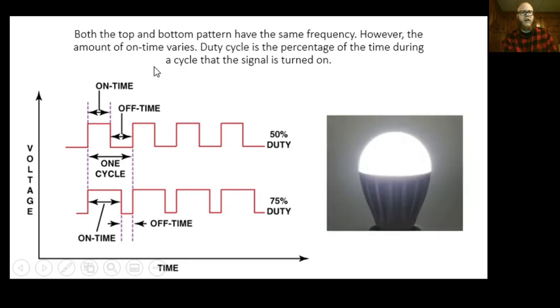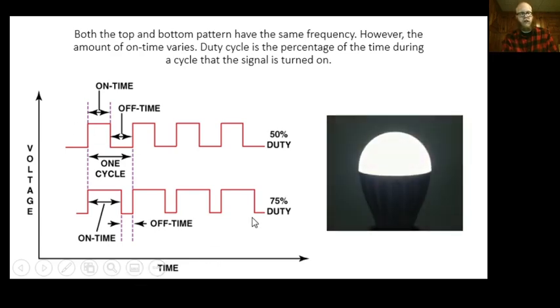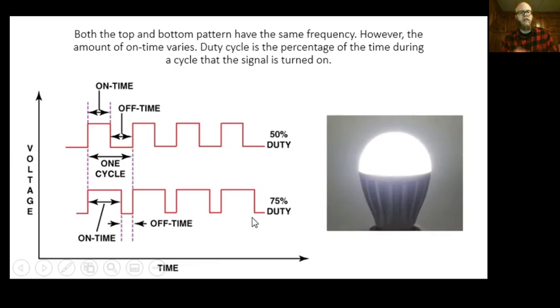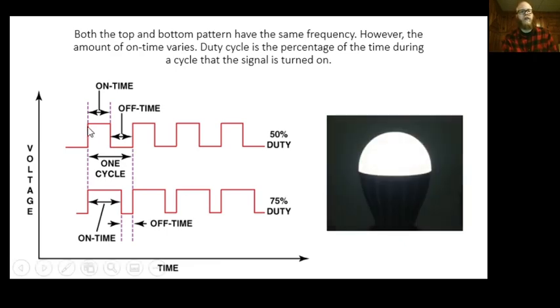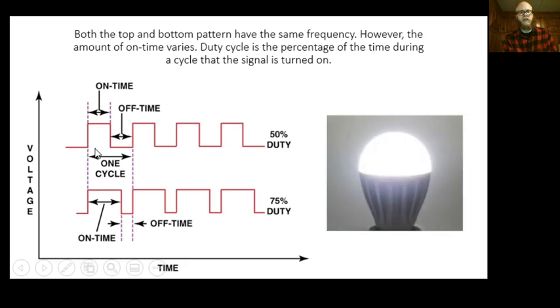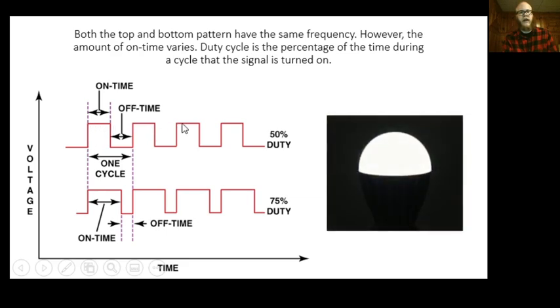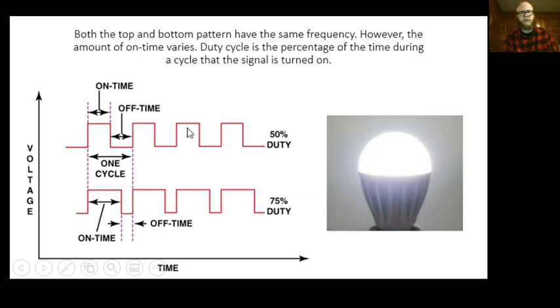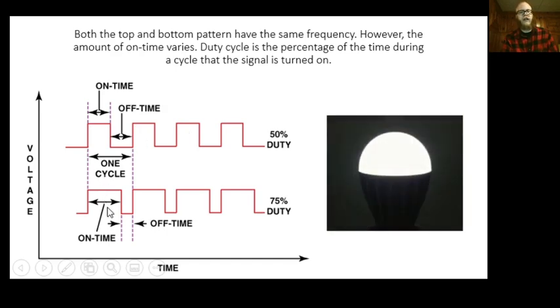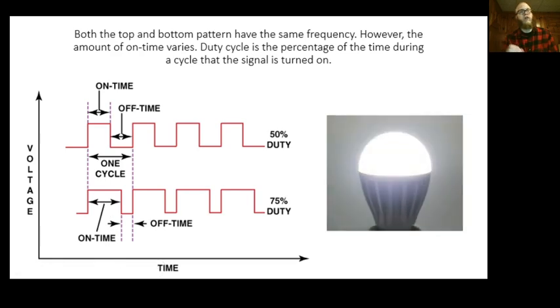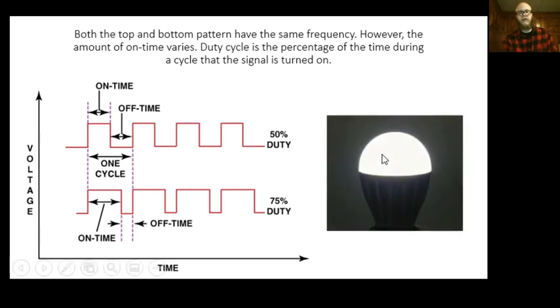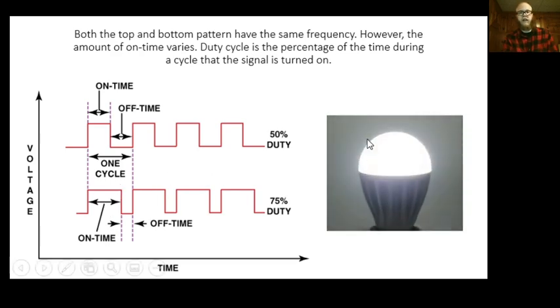On this instance, we're not given the time frame, we're not given the hertz rate because it doesn't really matter. It's got a cycle, and if I had 100% duty cycle, that would just mean I had a straight line of power, so it was just on all the way. As I would slow the motor down, or in the case of this image here, dim the bulb down, that's 100, 75, 50, 25, 15, right? It never got to 0 because it didn't turn all the way off.